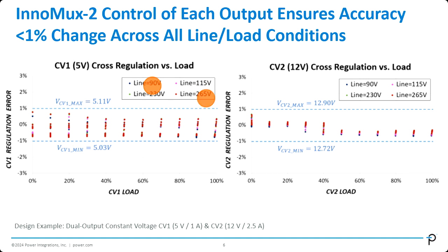And it also includes load changes on the 12-volt output. And on the 12-volt output, the load changes from absolutely no load to absolutely full load. So this set of data has included all of that. So even with all of that, you can see there's no issue with cross-regulation because our regulation accuracy is still staying within plus minus 1%.